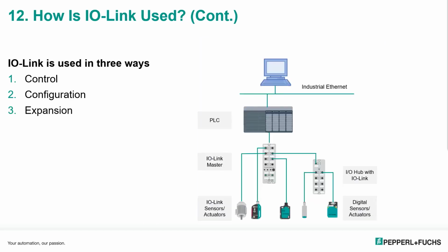And then sometimes IO Link is used, not like a network, but for expansion. We've got an IO Link device which is a hub, which you can connect a bunch of sensors to. You can imagine a spider web of IO Link hubs out there consolidating data and getting data back to the controller. However, you're not taking advantage of diagnostics down to the device when you do this, but I've seen quite a few customers use this just for sheer expansion.